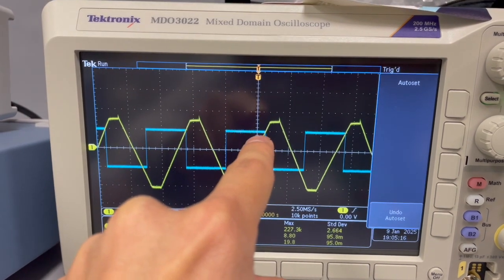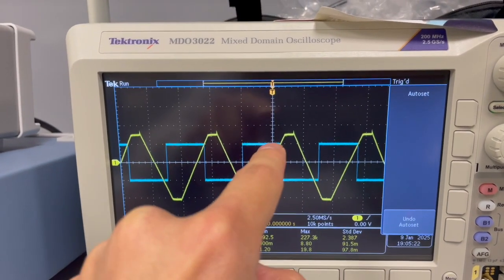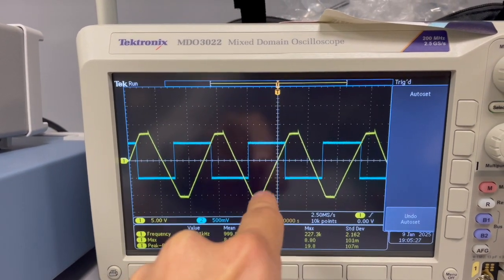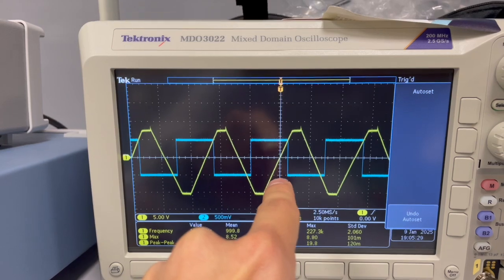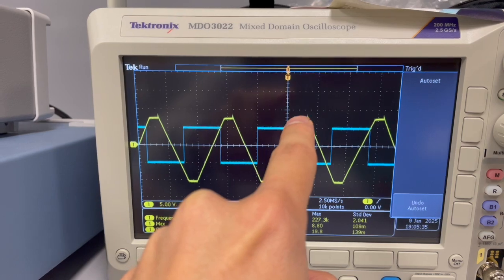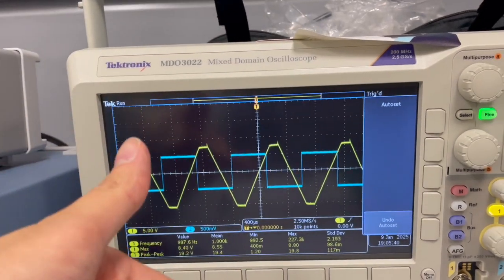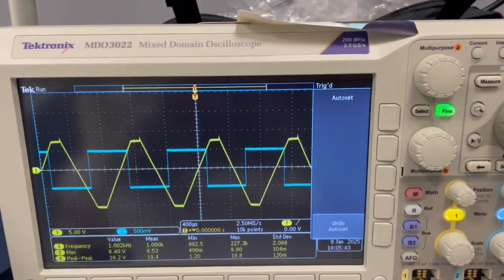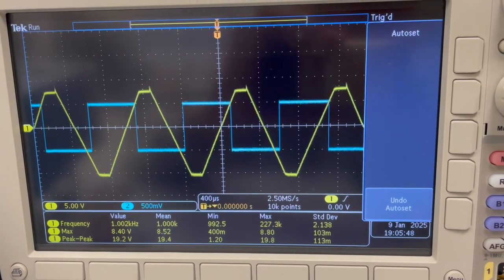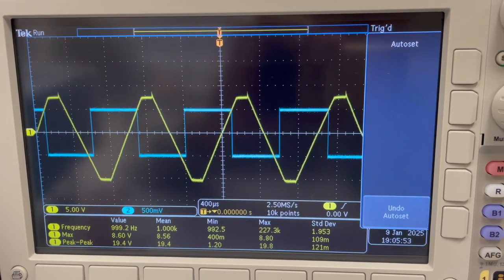But once the area drops to negative, it drastically changes to the negative. The area reaches the maximum, but then the area starts increasing, and the area of the output starts decreasing. So it's the opposite integration since it's in the inverting configuration. So we have the integration as it is. The integration of the square signal function gives us the triangle function.